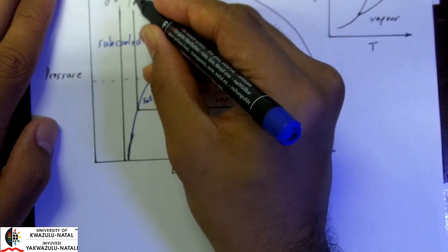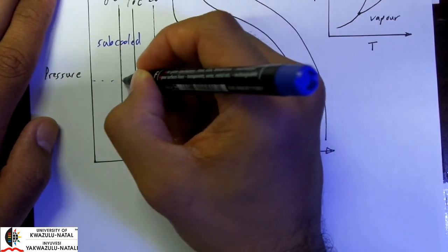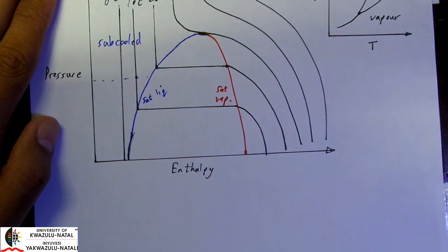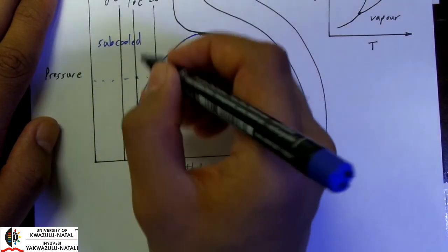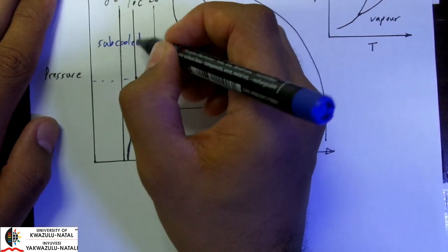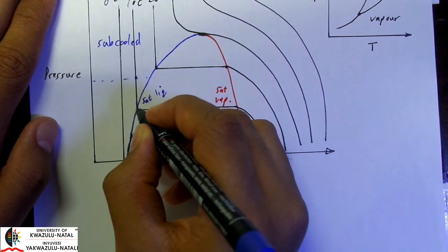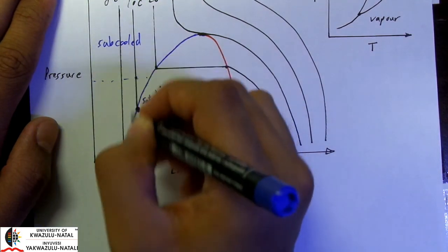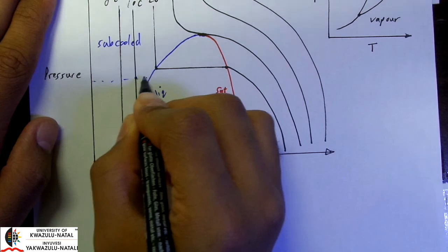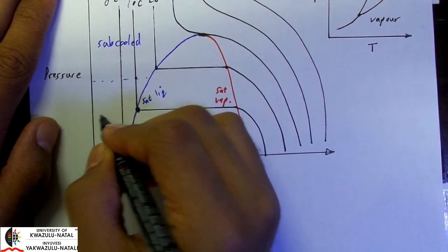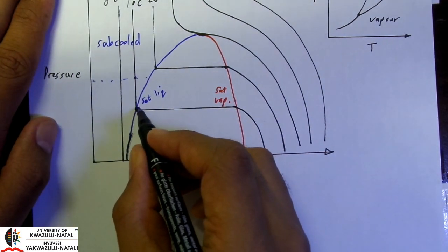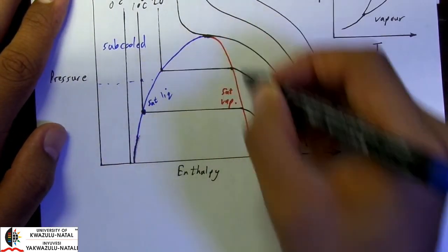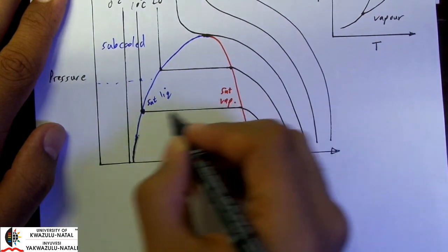However, let's look at the pattern of our isotherms. So once we are at 10 degrees, let's say if I want to heat further and add on more energy, then what's going to happen? Okay, now since our isotherm is leading down here right to our saturated liquid line, we ultimately, as we are increasing in enthalpy, should notice a pressure drop. And note that within this saturated region, my temperature is actually constant.